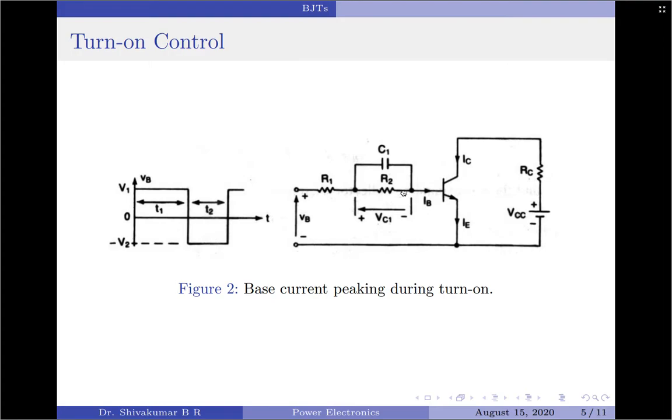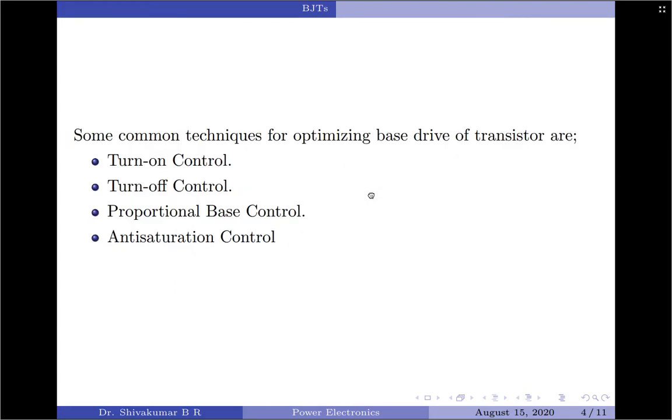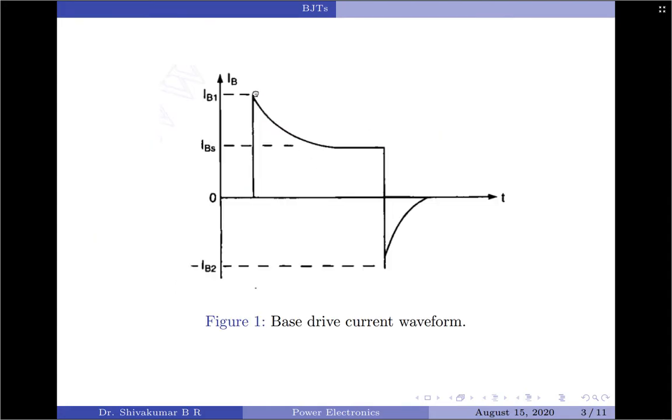circuit and the current always follows the path with the lowest resistance, and R2 is not considered at this particular stage. However, when the capacitor starts to slowly charge, the current starts to decrease because the overall resistance across the base steadily rises from R1 to R1 plus R2. That is why we will obtain a peak like this. So at time t equals 0, only R1 will be applicable, and that's why you will obtain the maximum base current at the BJT base.